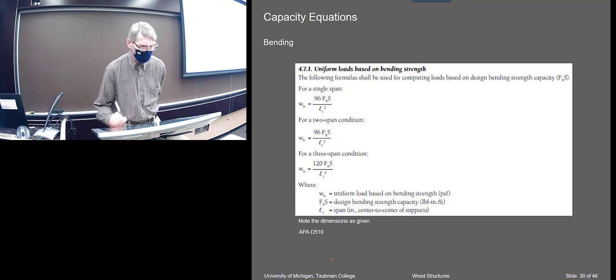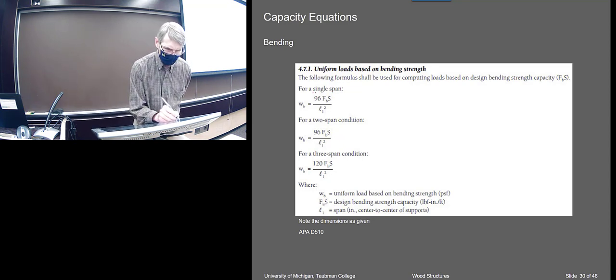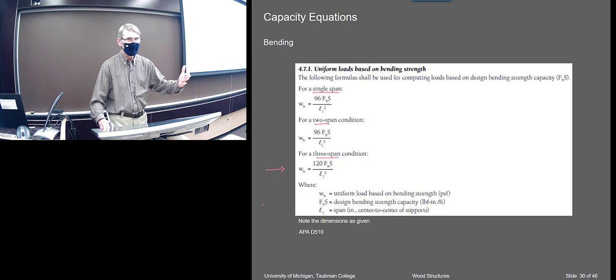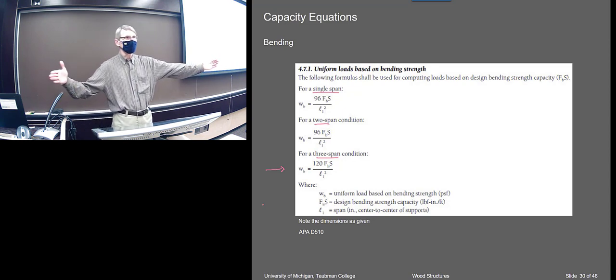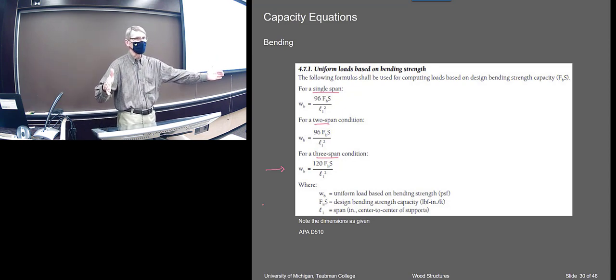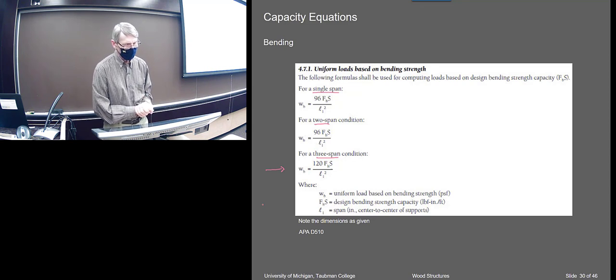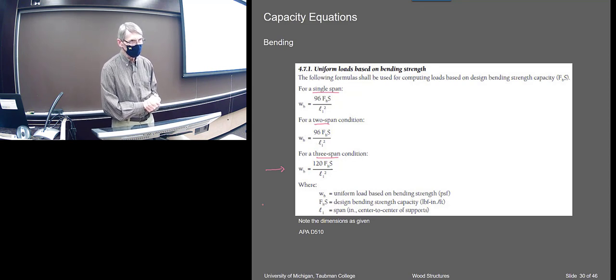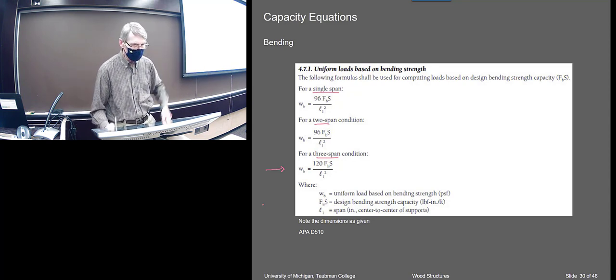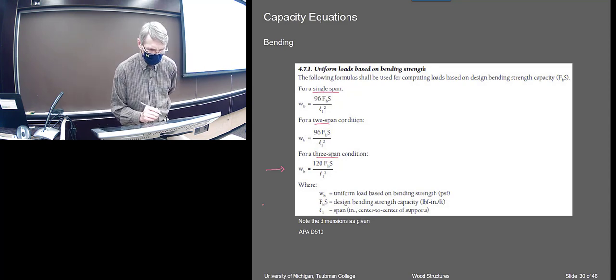They give you the equations based on single span, 2 span, or 3 span. Usually you're going to be, I mean, it's 8 feet long, for heaven's sakes. Hopefully it spans 3. Even 24 inches on center would give you 4 spans. So it should usually be in that category, but it depends, I guess.